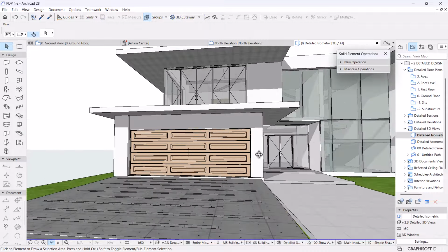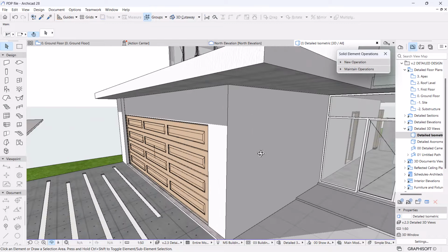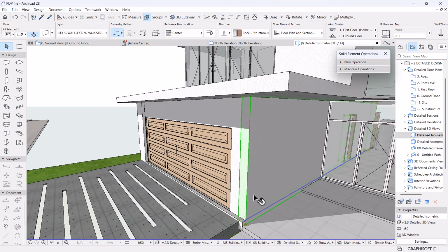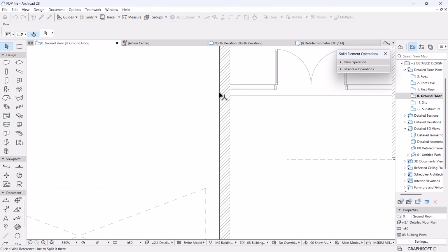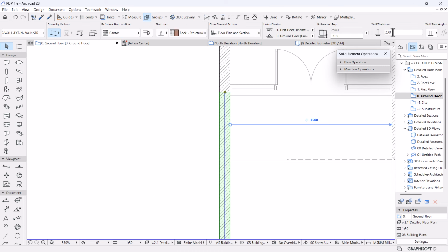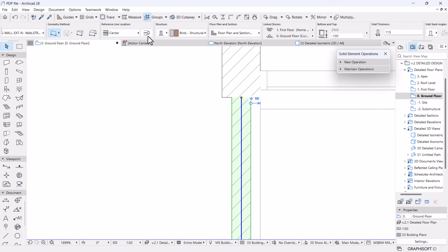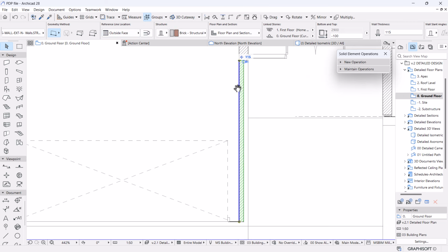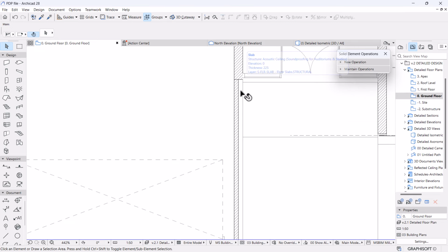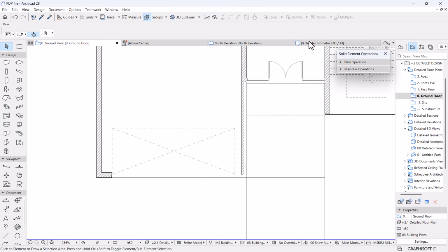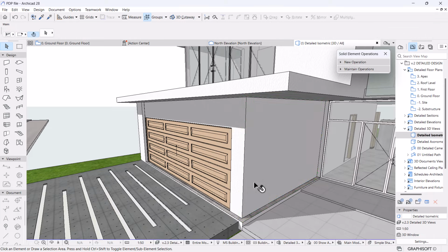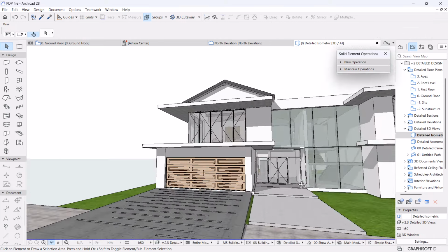From here, what we need to do, I'm going to set up even on this side. On this side is fine. We can split the wall as well. We need to split this wall into 2 parts here, and then set this to be half. Then I'm going to position it from the outside to there, so that I can have my cladding system running around and wrapping around, because I'm creating a hidden garage door. So yes, let's see how it comes about.